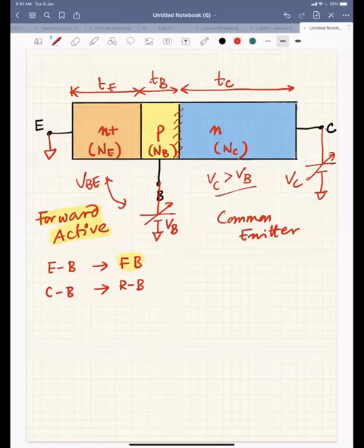And to forward bias the emitter base junction, you have to apply sufficient voltage so that this junction is forward biased. For silicon, we have already discussed that we are applying around 0.6 to 0.7 volt across this emitter base junction so that it is forward biased. So this is the forward active mode of operation, and we'll see the device operation in forward active, how the doping works, and we'll derive the equations of currents in the next class.